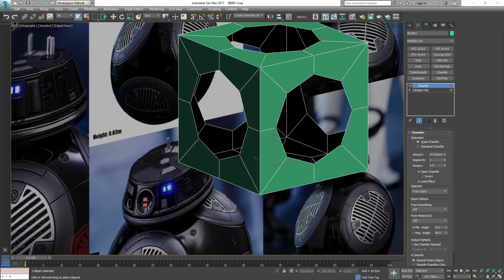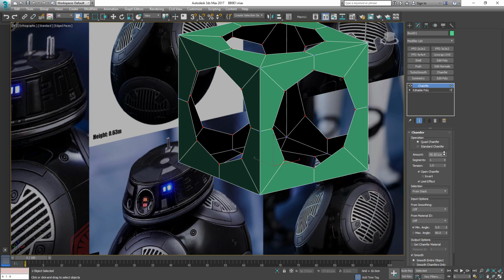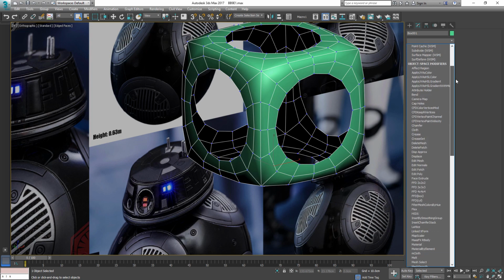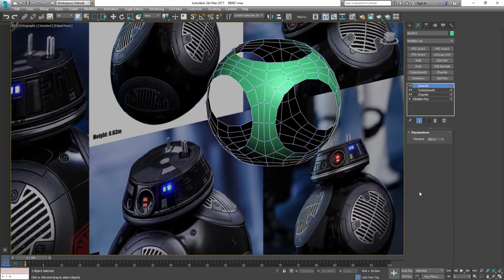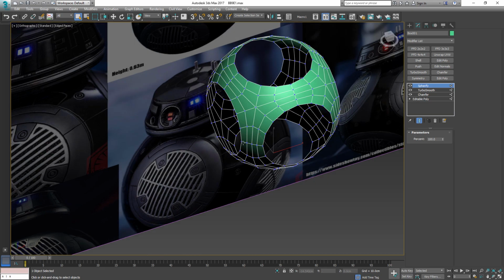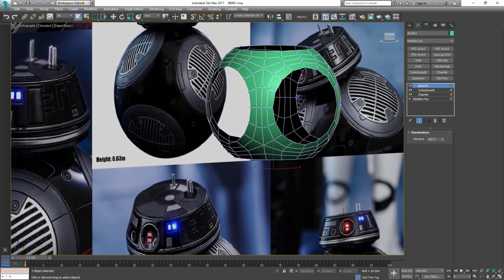We are determining the size here in between these two rings that you see there on the reference image. Feel free to use the exact same diameters that I'm using here, or amount. That way you have the exact same result. And I'm gonna add the Turbo Smooth modifier on top, and also the Spherify modifier, which I have to select through the stack. And now we have a nice and spherical shape here that already resembles our actual reference quite a bit more than the box did.